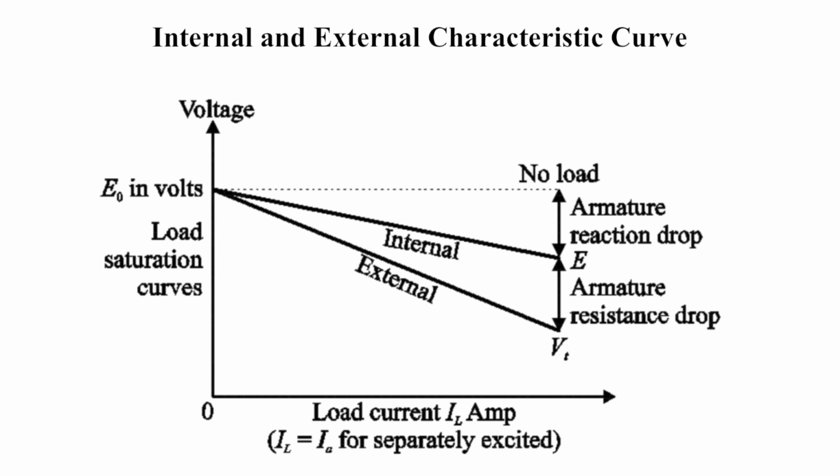We plot the graphs for constant field current in both the cases. In case of separately excited DC generator, induced EMF is totally dependent on flux phi, that is field current IF. Hence, to have control over the field current, in case of separately excited DC generators, field regulator is necessary.